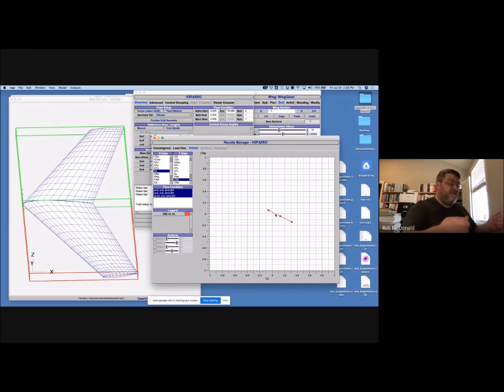And likewise for throttle, if you're climbing and you don't want to be climbing, you pull out the throttle a little. You put in a little less throttle. And if you do too much, then you're going to descend. Well, okay, if you're descending and you don't want to descend, then you give it a little more throttle. And you adjust it until you're flying along, hands off. The throttle's on a friction knob. It's not going to move. And the trim is on a friction knob. It's not going to move. And you're in trim. Your airspeed is in trim, which is lift, and your throttle is in trim, which is drag.